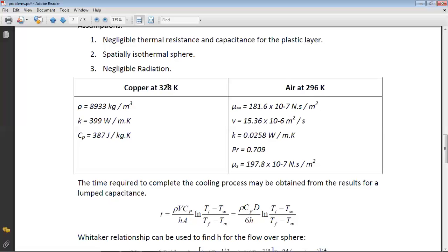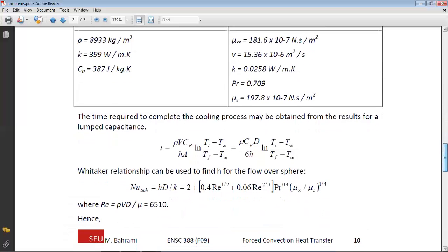This temperature should be 348. There is a small correction, make that. You get the values by taking the interpolation, because all the time you will not get the exact temperature in the data handbook. You may also be required to take linear interpolation for some values.